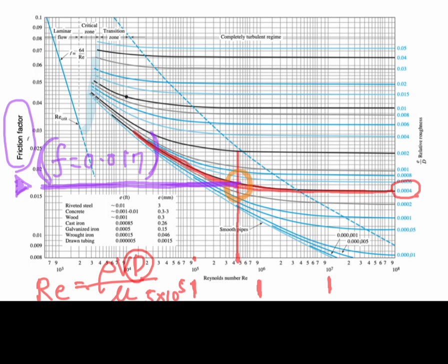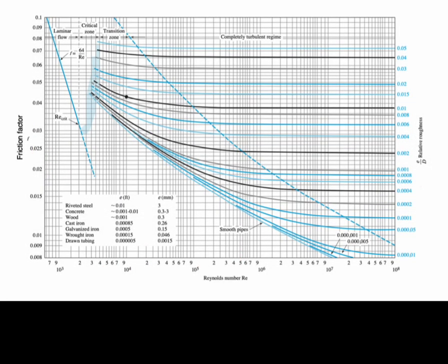Because this is very important, I hope all students could check their friction factor from the Moody chart. First, you need to find the relative roughness. For example, you get a relative roughness between these 2 points. What you need to do is draw your imaginary line first. For example, you get a value between 0.0002 and 0.0004.